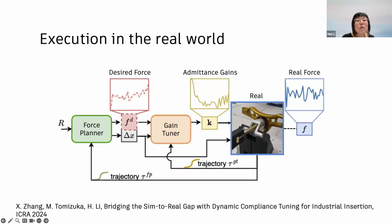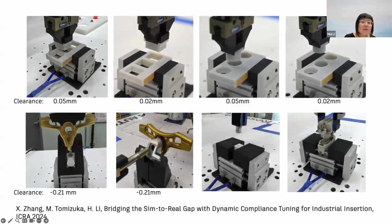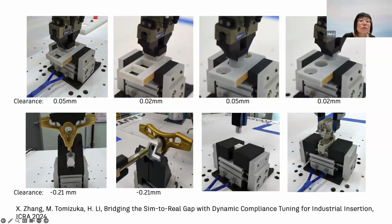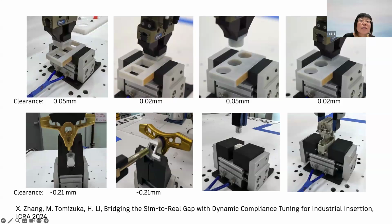And then the gain tuner tracks the desired contact force with the appropriate compliance gains. This way we could achieve pretty good sim-to-real transfer, as well as transfer to different insertion tasks. Here are some examples. On the top row, you see 3D printed peg and holes, but they have really tight clearance, 20 microns at the smallest. And fun fact, they're so tight that the pegs fall out of the gripper after insertion.